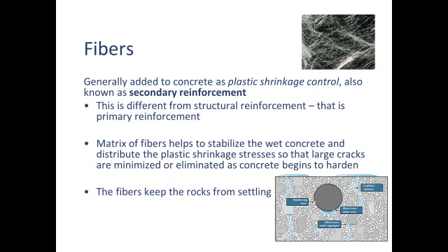So a whole host of problems come from trying to work on concrete that has too much mixed water in it, and from trying to finish concrete that has bleed water on it. All the problems are solved by mixing fibers into the concrete. What the fibers do is they keep the rocks from settling. And if you stop the rocks from settling, you stop the whole chain of events that leads to bleed water happening. That's why fibers are used in ordinary concrete. It has nothing to do with the hardened strength properties of the concrete. All they do is they keep the concrete from going bad. They don't actually make it better.